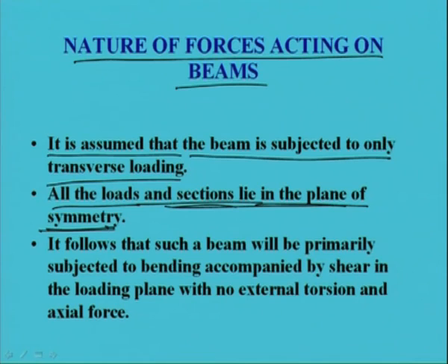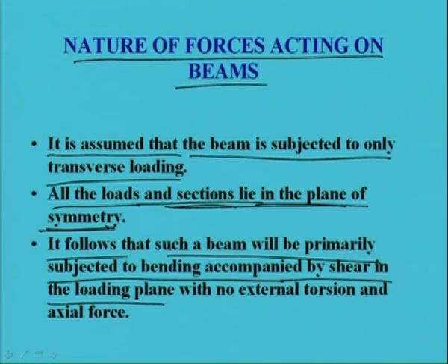So, with this symmetry, it follows that such a beam will be primarily subjected to bending accompanied by shear in the loading plane, with no external torsion and axial force. As we are assuming that only transverse load is coming into the picture and it is acting symmetrically, only flexural action and shear come into the picture, no torsion.